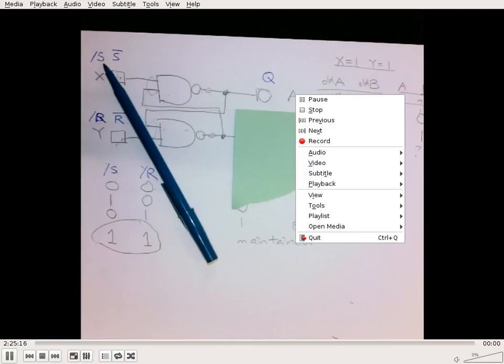Yeah. So what they do is they use MOV components, or metal oxide... I don't remember what V stands for. Varistor. Okay, thank you. So it's basically a self-sacrificing component where it just dies. In the case of a normal surge, computers don't have those, right? It depends, I have no idea, because it's an added expense. It's not like people do not know how to protect computers from surge. It's just that they need to add some additional components to do it.